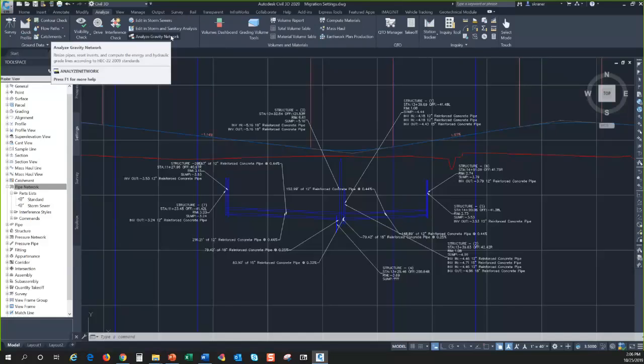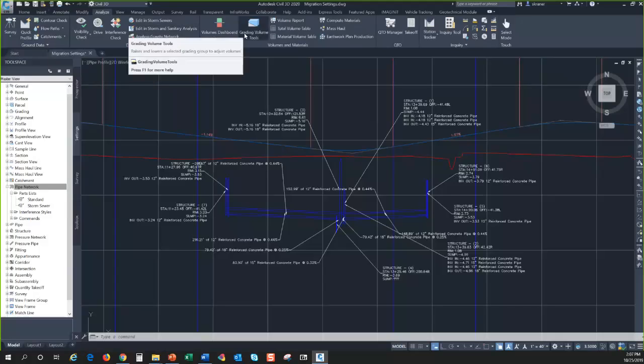Does the TC automatically adjust to account for pipe travel time? The TC that you input is the TC of the drainage area. The TC that Hydraflow calculates gets calculated iteratively, especially if you pick the method that I discussed, the enhanced modeling method, where it calculates 3 iterations trying to balance the TC with the HGL to get them as accurately balanced as possible.